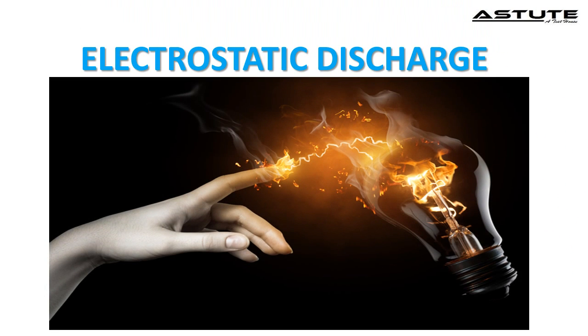Static charge is an unbalanced electrical charge at rest. Typically, it is created by insulator surfaces rubbing together or pulling apart. When a static charge moves from one surface to another, it becomes ESD. When that static charge is discharged through equipment, the equipment can be damaged. So in the ESD test we can test the equipment's capacity to withstand that static charge discharge.